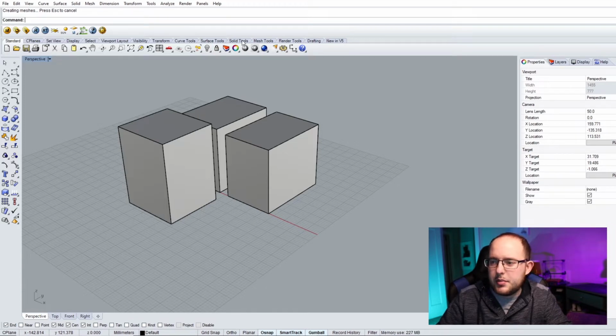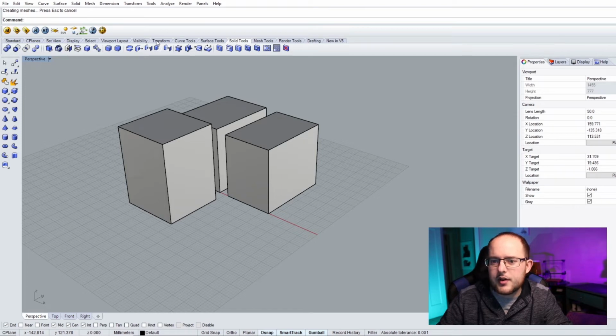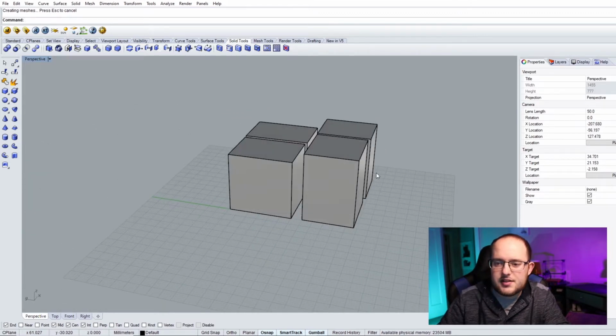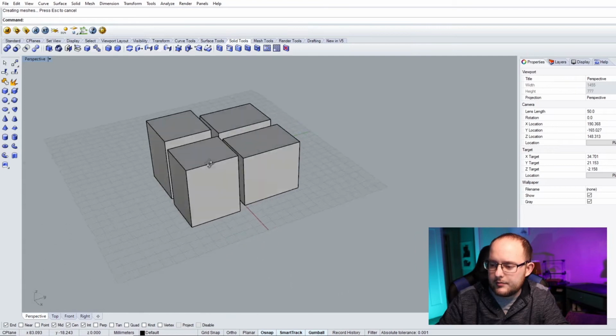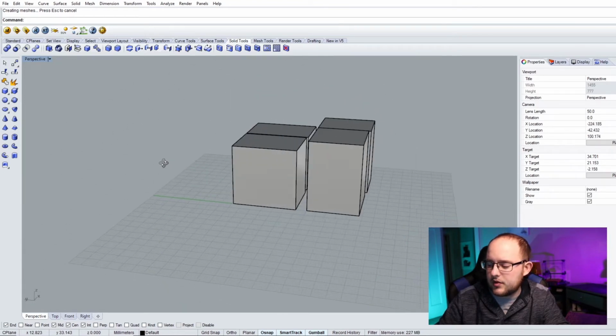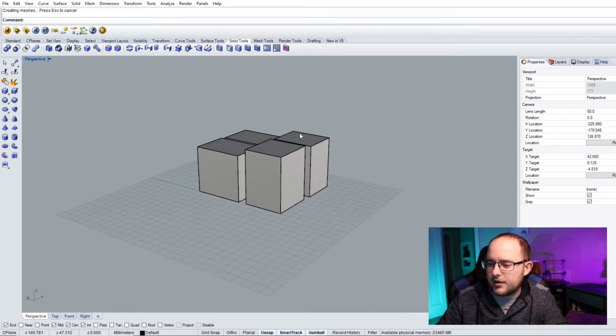Another way to do a box right here, if you just go back to solid tools right here, this is the same as this solid pull down up here. So I click solid, and then if I go right here to box, we just got a box right there, same thing. So it's very user friendly in that sense, that there's multiple ways to do something, whatever you're most comfortable and easy for you. But yeah, right now I'm just holding down the right mouse button and orbiting around.